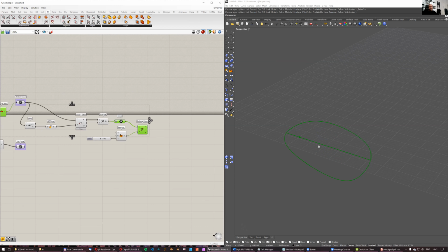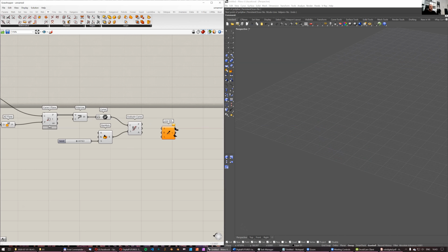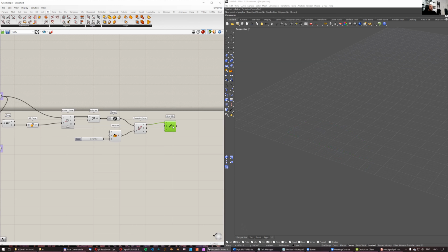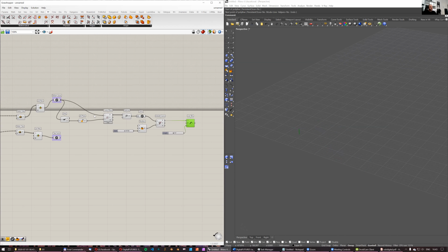and I will draw a line that is 7 centimeters long, or actually I don't know how long, because I'm in a different scale. So let's say 3 units, 3 millimeters. That is my scale here. So I will draw a line SDL, start, direction, length. From this point, I will specify the direction a little bit later, and I will say it should be 3 units long. And the direction should be a vector from the first point to the second point.